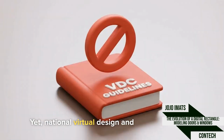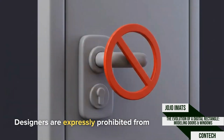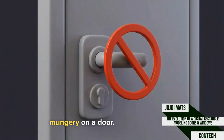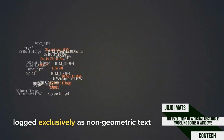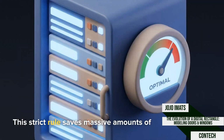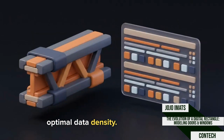Yet, National Virtual Design and Construction Guidelines issue a strict warning to designers as the component matures. Do not over-model. Designers are expressly prohibited from building 3D doorknobs or physical ironmongery on a door. Every piece of ironmongery must be logged exclusively as non-geometric text data in a schedule. This strict rule saves massive amounts of computing power. True BIM maturity requires balancing the necessity of a geometric shape with optimal data density.